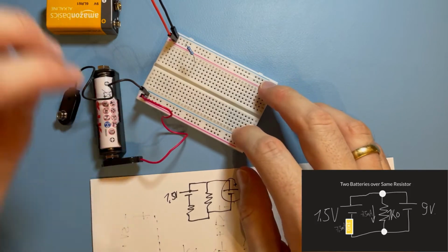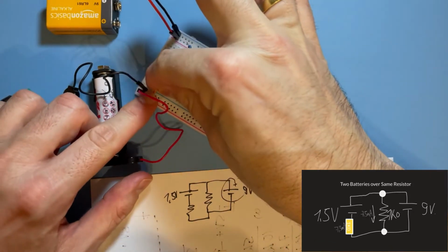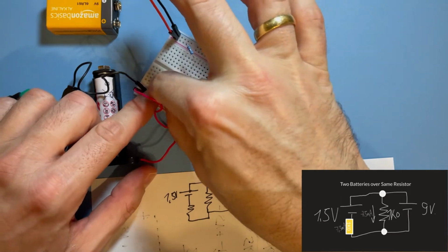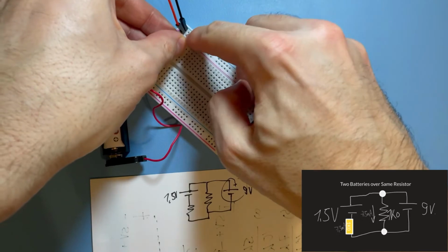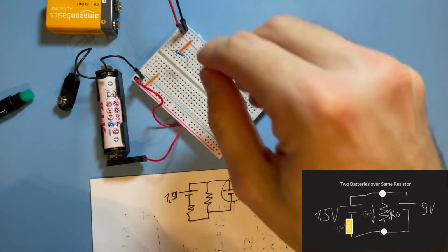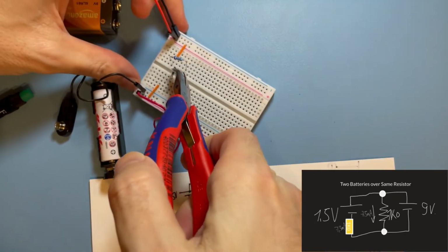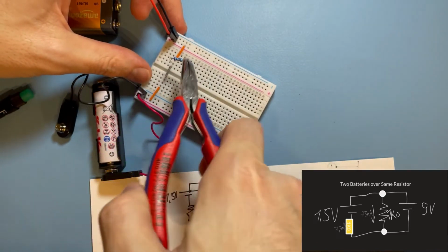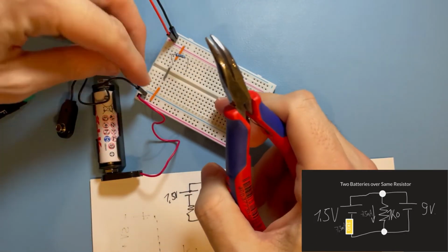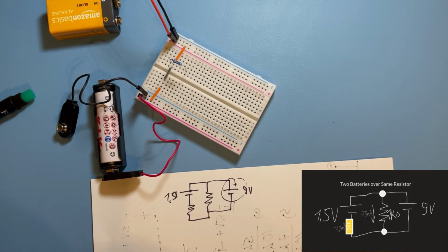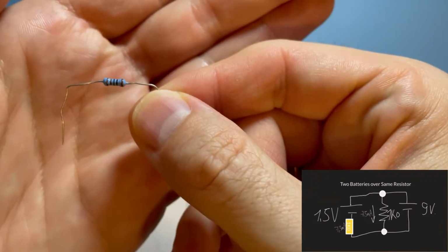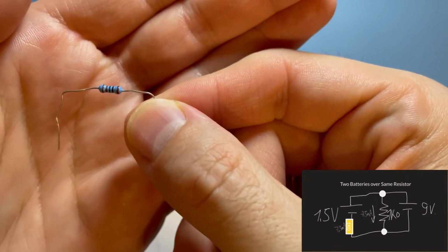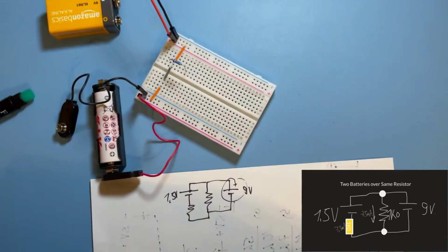Let's do that. We connect this here to the other positive rail, going through. We can connect then here. Then we said we wanted to have another 1000 ohm resistor. Oh, what is this? Hope you see it. It's brown to the right, then black, brown. That's exactly what we want.